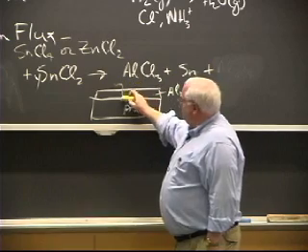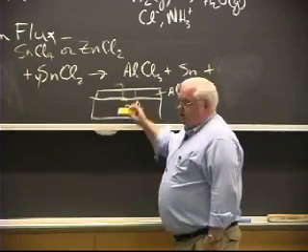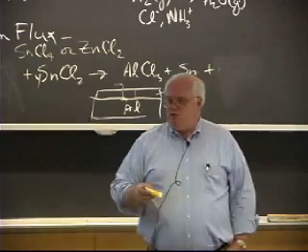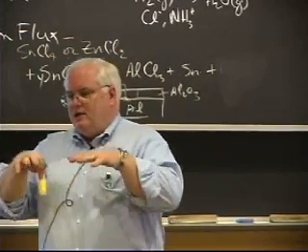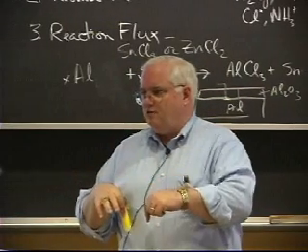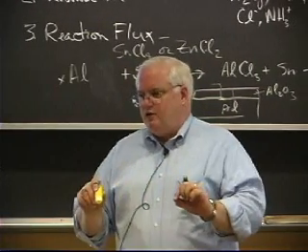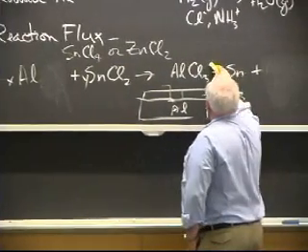And it only takes, remember, 300 degrees to get a thermal expansion mismatch, typically, that's going to cause little micro fissures. So I have this molten flux on top of the aluminum oxide. I heat things up, you get these little micro fissures. The tin chloride finds its way down those micro fissures to the aluminum. Aluminum trichloride at these temperatures goes off as a gas.